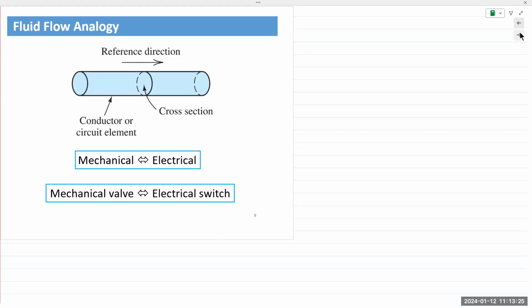That is also the operating principle of an electrical fuse. An electrical fuse has a small piece of wire inside it. It has a certain power rating. If the current flowing through that wire exceeds the rating, it cannot handle it and it just blows out. When you say a fuse blows out, that is what is happening. It's actually breaking, and when it breaks, the circuit is now open. There is no pathway for the current to flow through. So it's used for circuit protection, right?